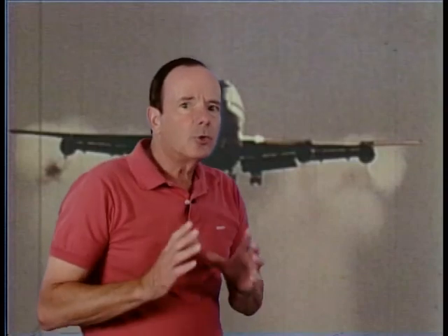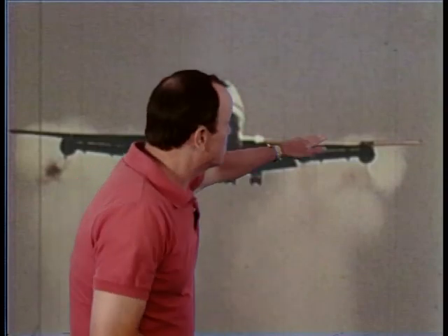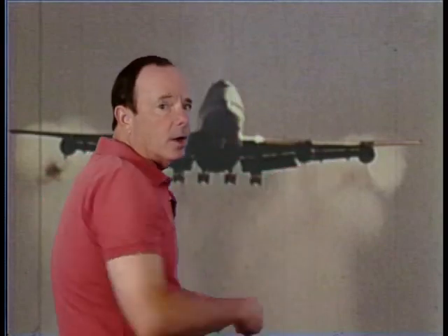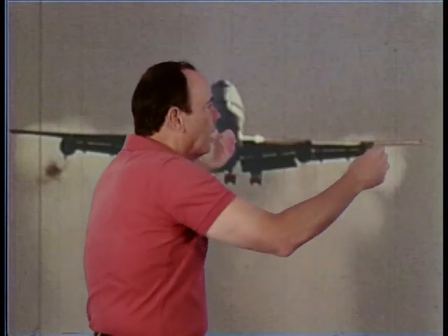So if you were an aircraft designer and you wanted to eliminate or at least reduce these wingtip vortices and reduce the drag that they cause, they decrease lift and increase drag. Well, one way to do it would be to put a real long high aspect ratio wing on the aircraft, like you have on that beautiful glider we saw earlier. Well, the problem with a high aspect ratio wing on an airliner is it would be very, very structurally difficult to do, and it might be heavy and it'd be hard to make it strong enough. So there is a very simple, elegant way to solve that problem, and that is with what is called a winglet. Now, a winglet is installed on the wingtip like so.